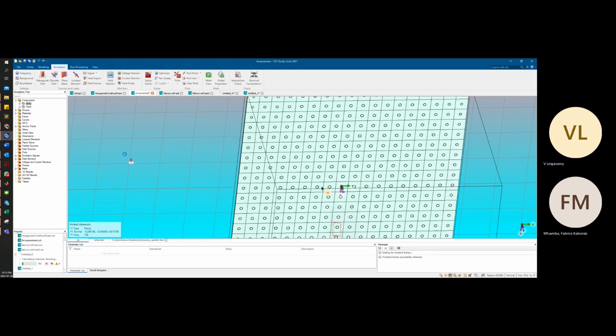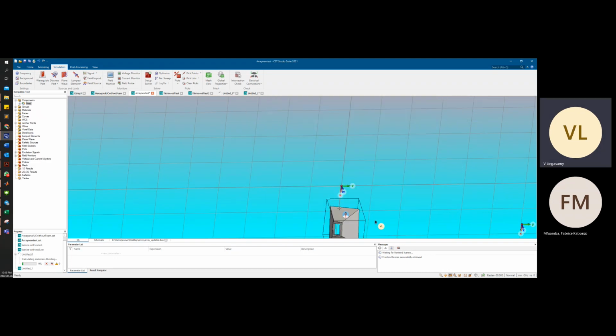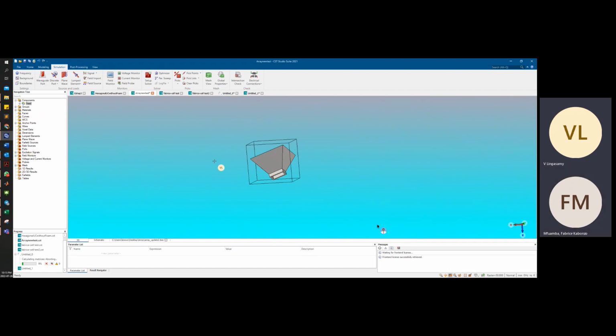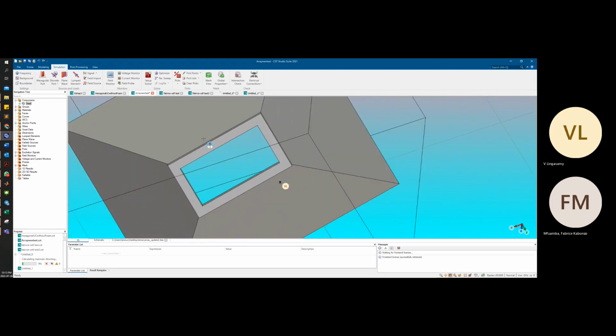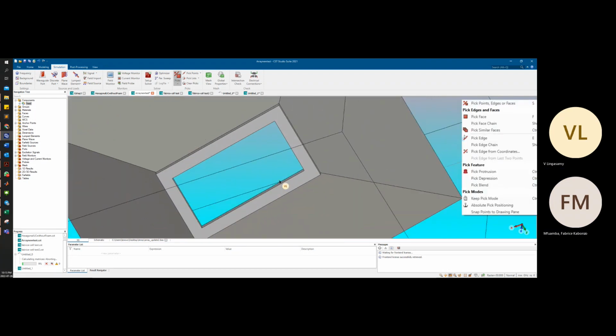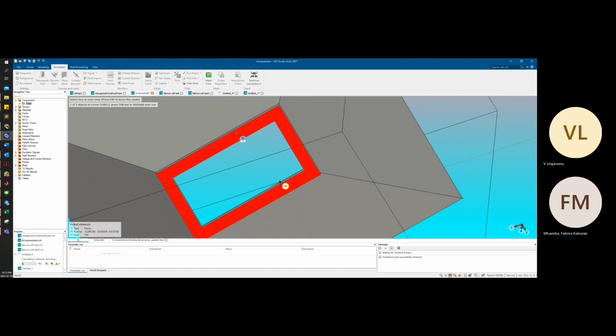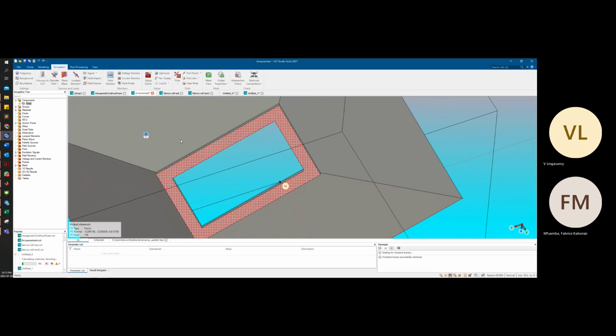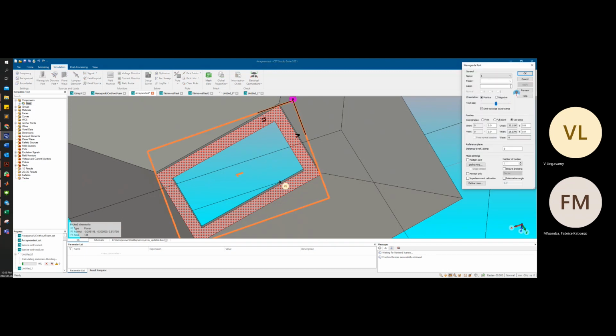Delete this, and then we'll just fix the horn antenna now. So you have offset it, right? Can you assign the port now? Assign the waveguide port. I think this is the problem.